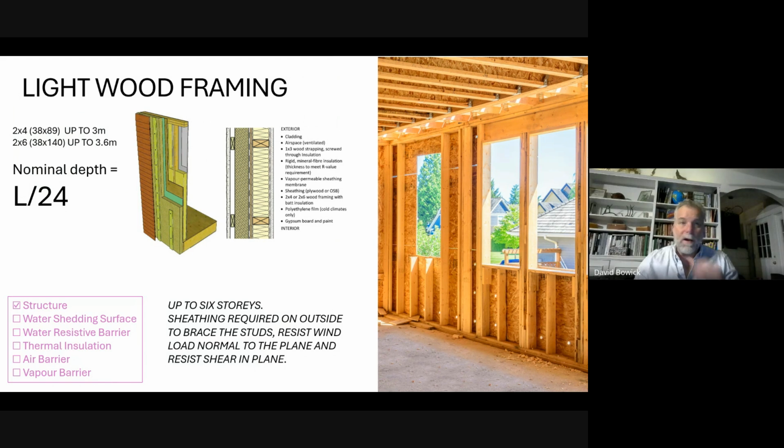There are a bunch of products on the market now that are insulated sheathings. I think they might call it zip sheathing or something. There are products on the market that are insulated sheathing that don't have wood directly in contact with the stud. This can be beneficial because it prevents a thermal break, a cold bridge. It allows you to build it without the layer of insulation on the outside of the sheathing. So it's beneficial in that respect, but it's structurally a bit problematic.